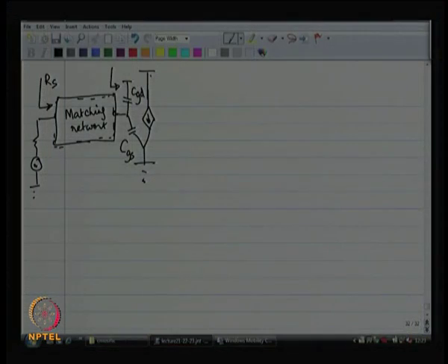You are always going to see a capacitance, or you are always going to see something which is lossless. There is no power consumption in this, right. So, the idea is, do not think of the MOSFET as just a capacitor. It is unwise to think of the MOSFET as just a capacitor. It is not. First of all, there is gate resistance.